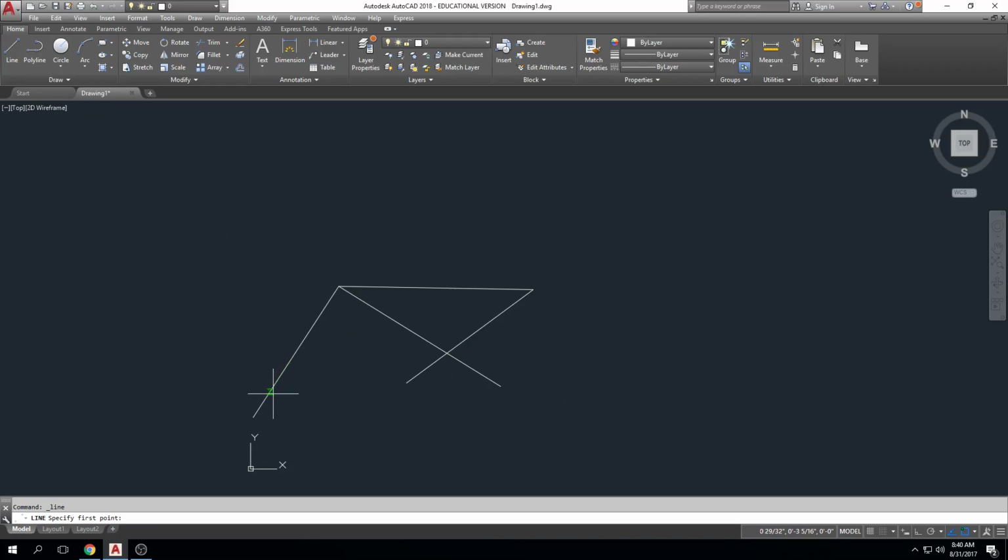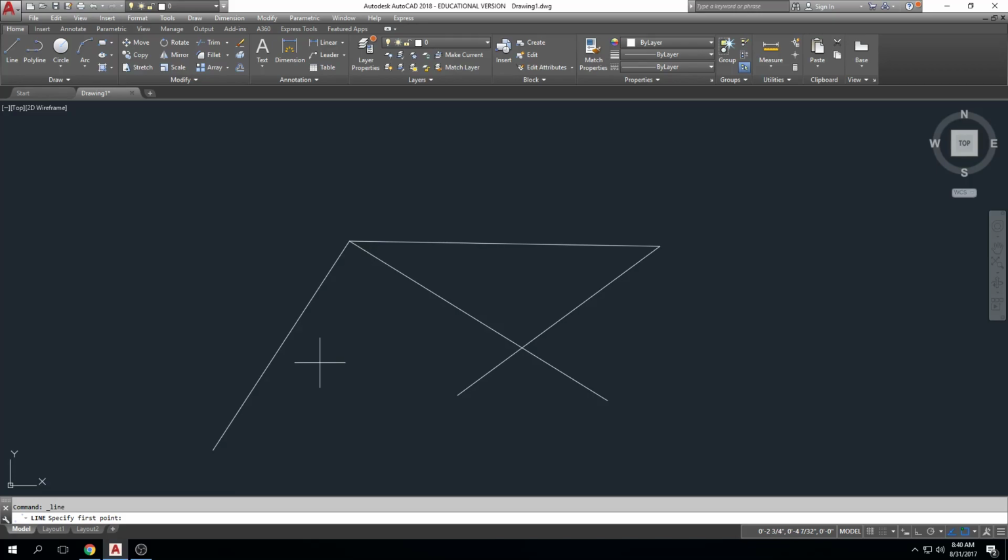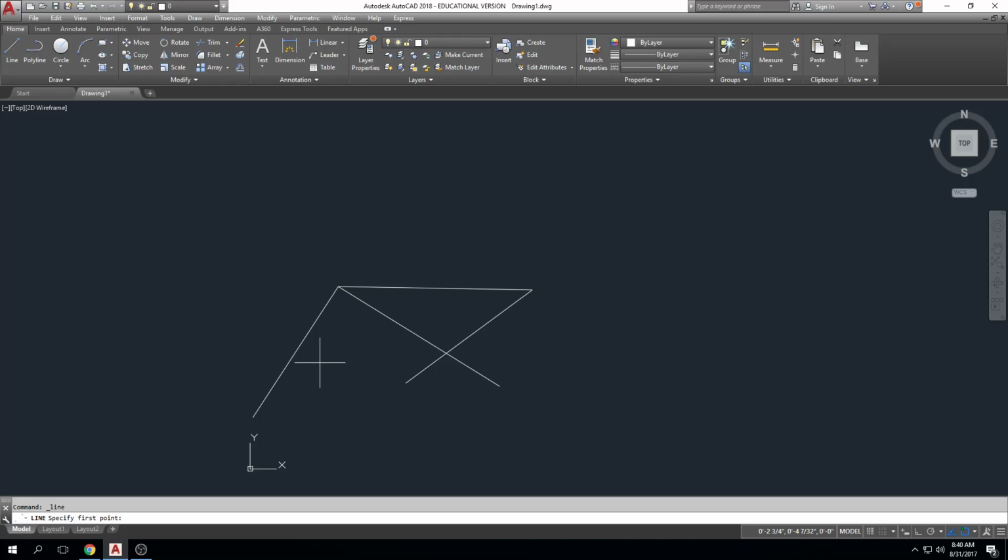but the midpoint wasn't engaging. Okay, the endpoint engaged. AutoCAD will by default try to sense the closest snap, but every now and again, if you're zoomed out or in a weird angle or space next to an object, or if you're in a spot where there's a lot of things very close together, it won't quite know which one you want, and it will just start sensing all over the place, right?